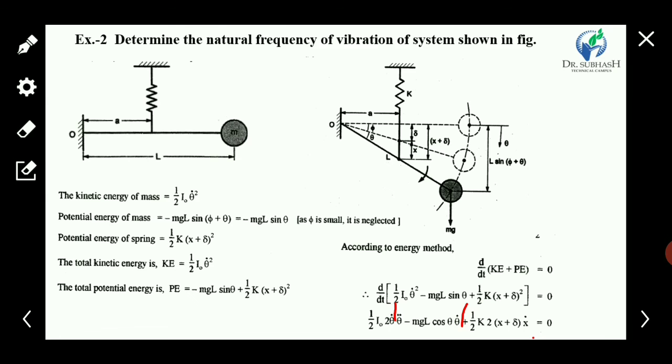How is it equal? It is torque equality. We know that earlier, if only the rod is there and no weight is there, the spring is in equilibrium condition. But when the weight is connected to the rod, the spring deflects slightly from its position by delta.